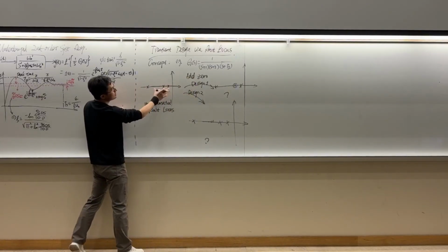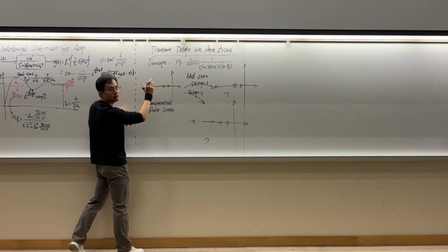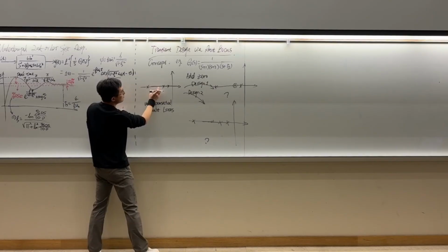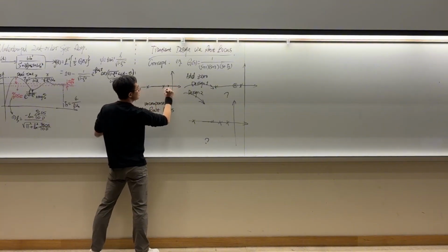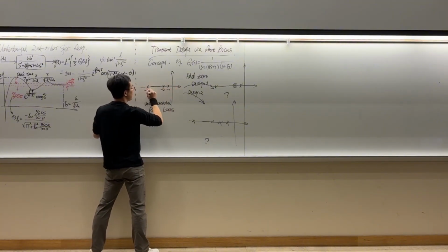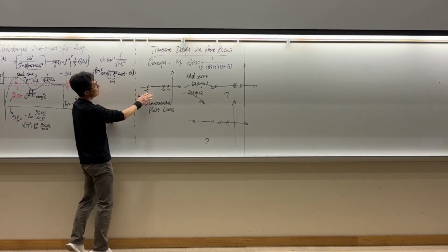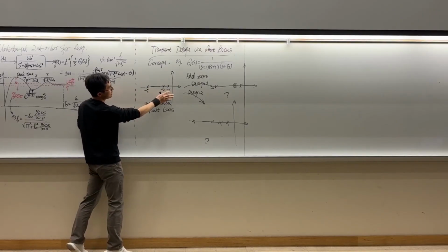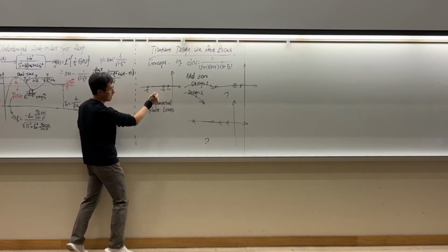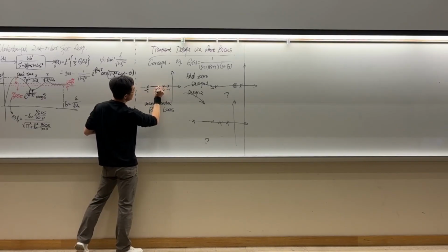It has 3 poles, so you can calculate the asymptote angles and centroid. The centroid is going to be the geometric center of these 3 poles. There are no finite zeros. This is -1, -2, -5. So the average is going to be 5 plus 2 plus 1, 8, divided by 3. It's going to be roughly about here.